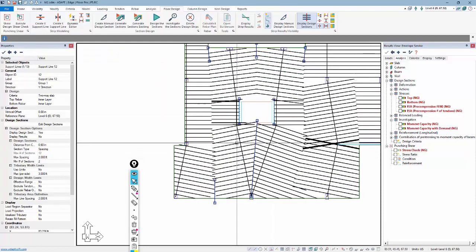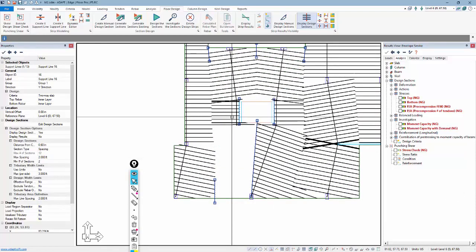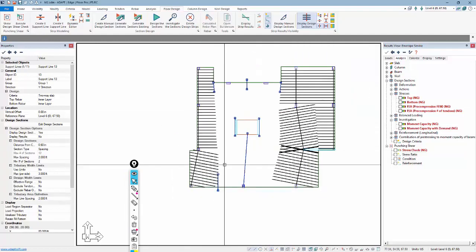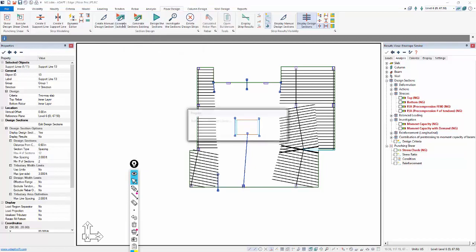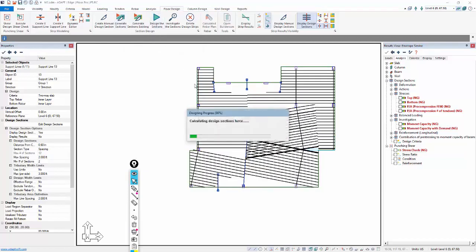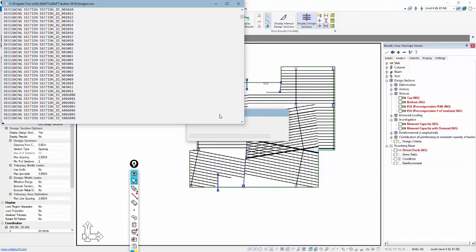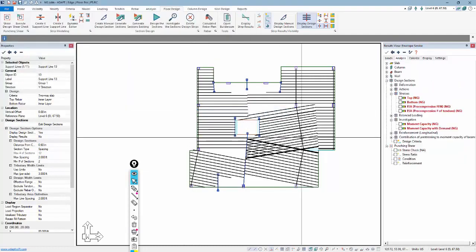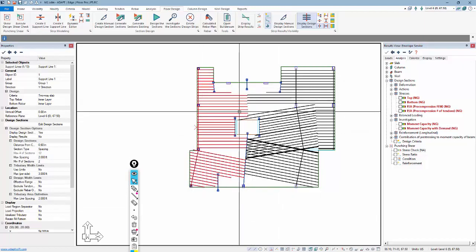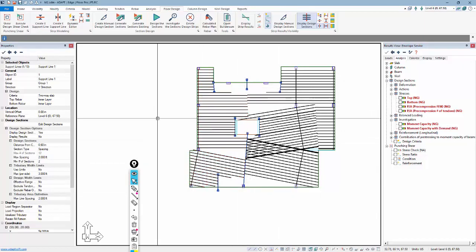So let's try this. I'm going to get rid of these two strips to see if we can get results that we want to show here. Let's go back and regenerate and design. Oops, let me add some splitters there. Because I removed those, these are now stretching over to just the created tributary boundary towards that inner wall.